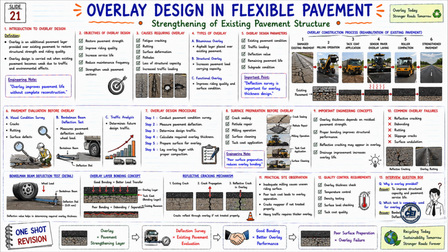Now important engineering concepts. Overlay thickness depends on residual pavement strength. Improves structural performance. Reflective cracking may be visible in the overlay. Increases overlay life. And these concepts are most important in practical rehabilitation design. Now let us look at the 10th topic.